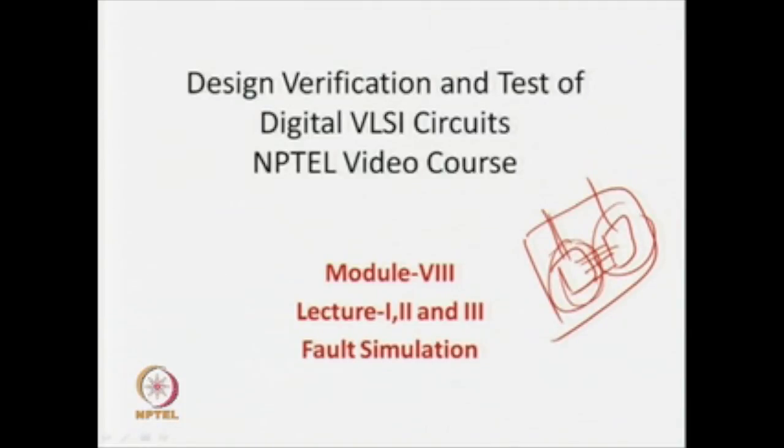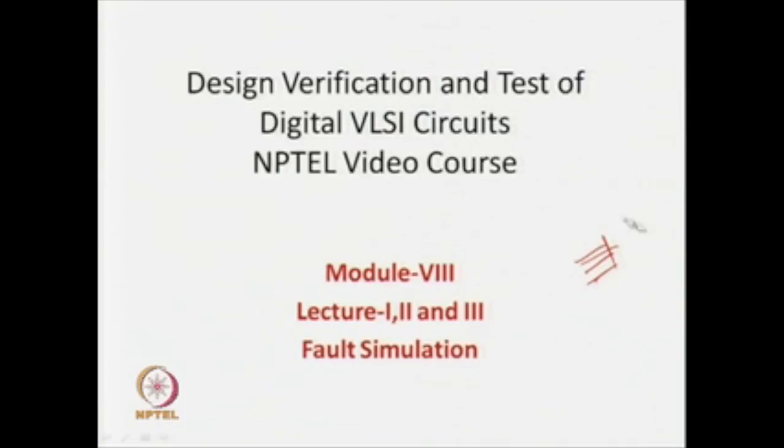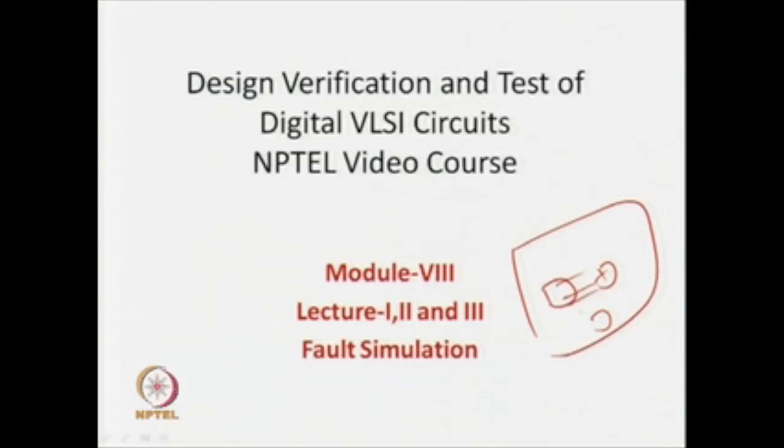On the other hand, if you make small modules of your whole circuit, then the number of input patterns per module is very small, which is an advantage, but the number of intermediary lines between the modules is very high, and controlling and observing them remains a challenge, for which you need either pinouts, or multiplexing arrangements, or a shift register and so forth.